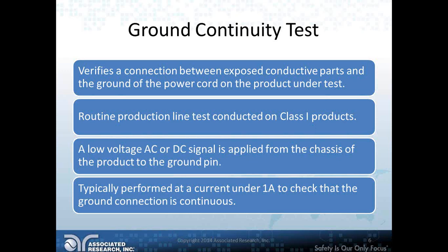If or when an insulation fault develops between the line circuit and the exposed metal parts, the ground conductor provides a path for the dangerous fault currents to return to the system ground at the supply source of the current. If this ground circuit is of a low enough impedance or resistance, the current will circulate through the ground conductor of the equipment, thus enabling the circuit breakers or fuses to open.